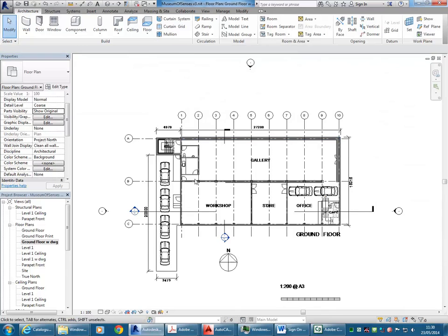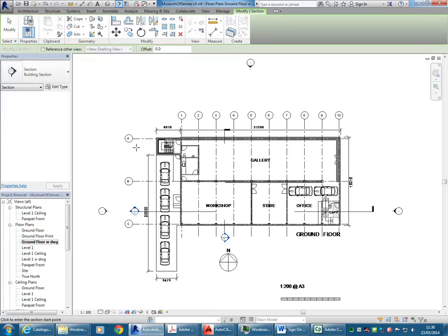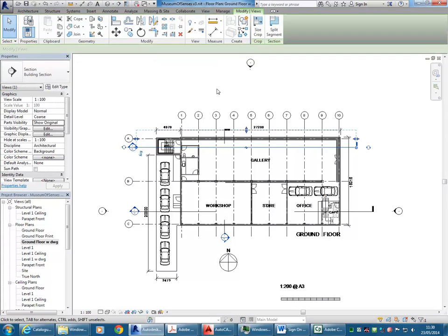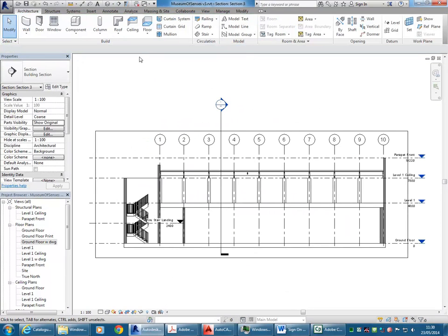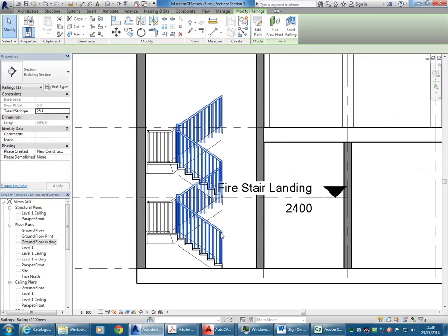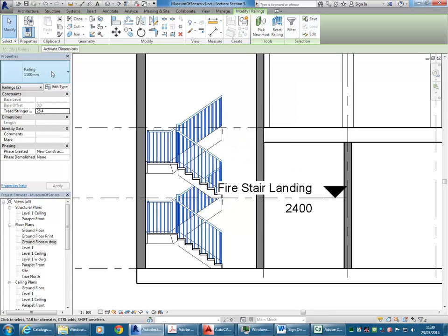And I'll just do a new section. So it will figure out how to get there. Yeah. So because you put the top at level 1, it knows that it needs to double what you just drawn. Yeah. Wow. So if you had put the top to level 2, it would still do that. If they're even, the limitation is they have to be even. But yeah, it will do that, exactly. Yeah, set up the geometry of the basic layout. Yep, that's right, exactly.